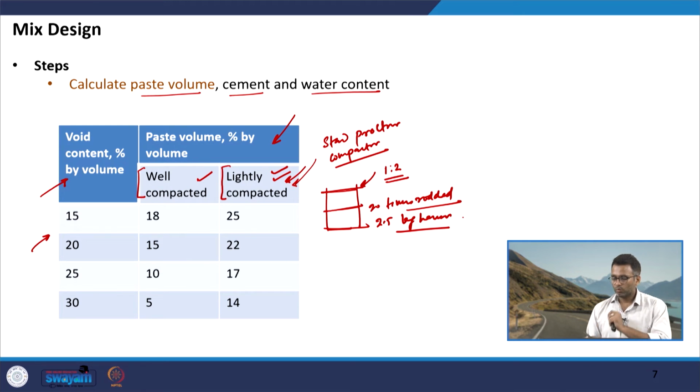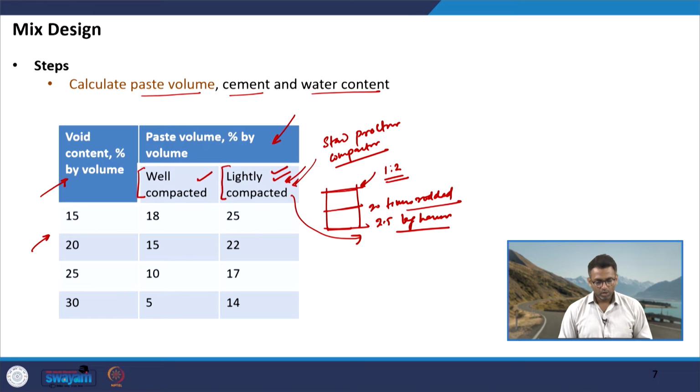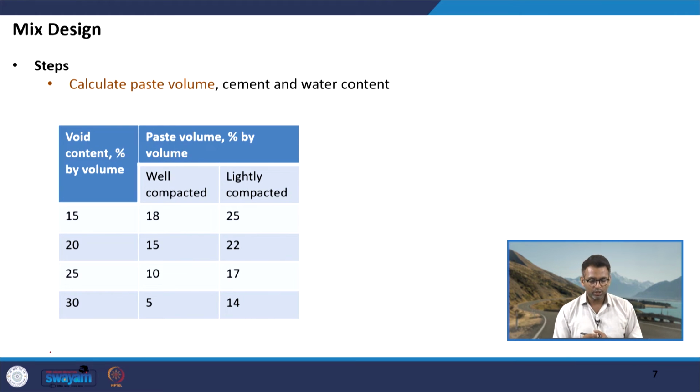Okay. So, I am anticipating that this light compaction refers to something similar to what we are discussing now. Well, maybe well compacted mixtures are those which can be compacted using heavy compaction, but in case of pervious concrete, again too heavy compaction can lead to breaking of the aggregates. So, it is not very well established what we specifically mean by well and lightly compacted mixtures. That is a different thing here, but say we have two options, well compacted and lightly compacted.